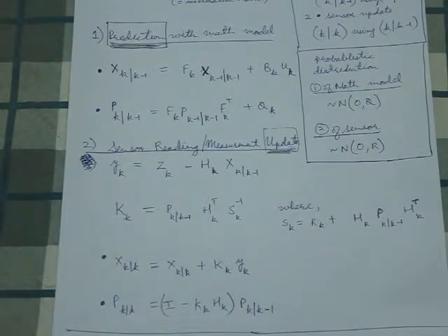Based on the sensor and based on the type and the number of outputs that the sensor gives out, the H matrix may vary from sensor to sensor. For the LiDAR, since only the position is given, we have to extract only the position section of the state vector.